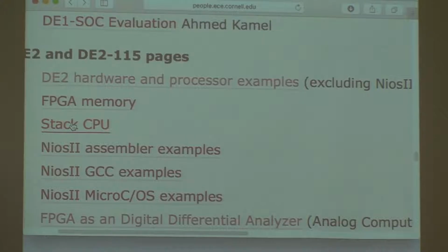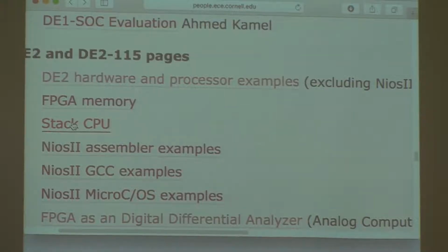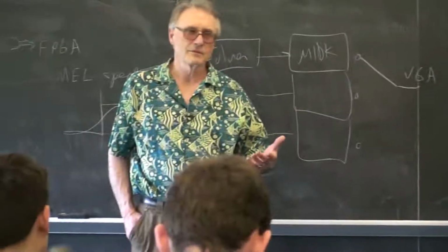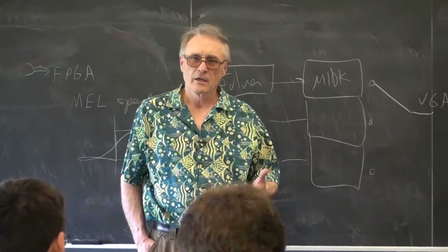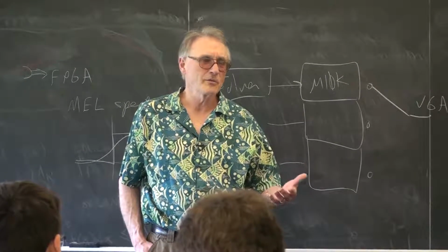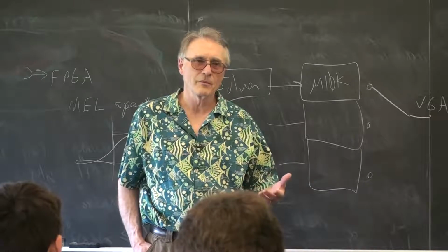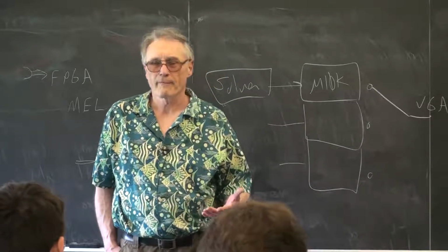The reason I was playing around with a stack CPU originally was that I didn't like the NIOS processor, which was the old MIPS-like processor that was part of the IP from Altera, because there was too much hidden. You couldn't see the Verilog because it's encrypted, so you can't figure out how it actually works. The tool chain is kind of difficult to set up and understand. And so I wanted to have my own CPU with my own tool chain so I could play with it. Well, that's why I did this.